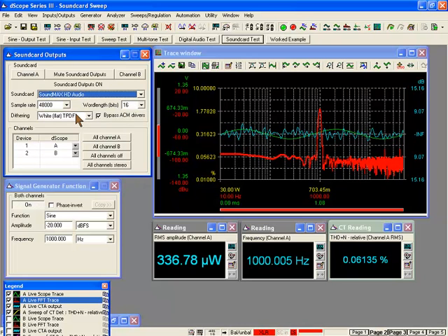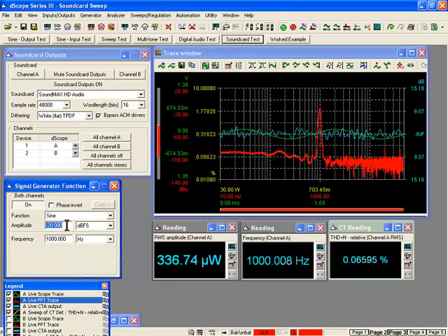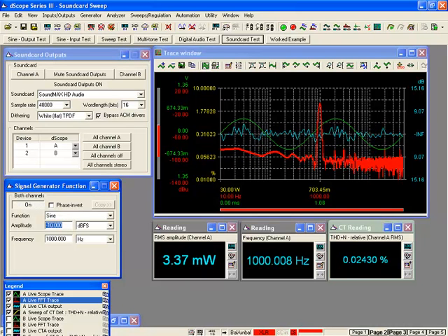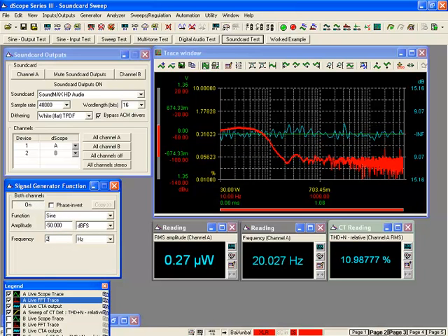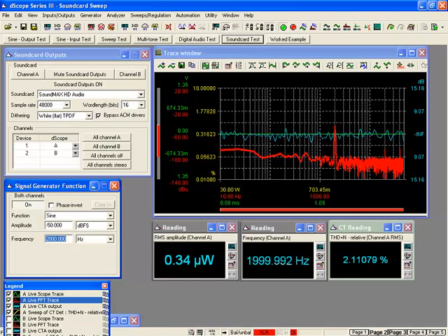you can now hear and see that I'm generating a test tone at the output of my laptop sound card, and I can now choose whatever amplitude, whatever frequency I like. So I have closed loop control once again of my laptop sound card, and that allows me to perform sweep measurements, sinusoidal measurements, multitone measurements, all of the types of tests that we've talked about without needing to use any WAV files.